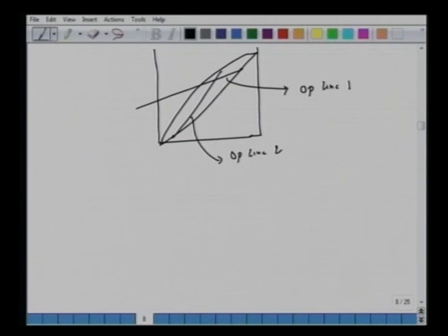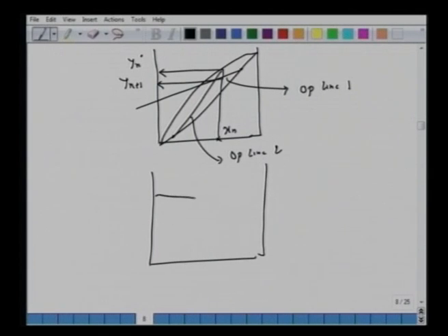So what it does for a given mole fraction x, if you go to the operating line, if this is xn, this will give you yn plus 1, and for the same xn, here you have yn star, or vice versa. We talk of this Ponchon-Savarit method instead of the McCabe-Thiele method. We have the enthalpy curve for HV and we have HL.